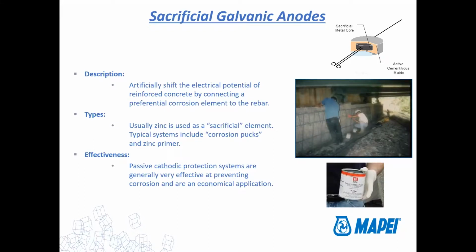It's going to be time limited depending on how much zinc you use. So typically 100 grams or so is kind of the average amount. But you can get anodes that are up to 300-400 grams of zinc. You can get them as small as some manufacturers are selling, like 38 grams. But the more zinc you use, the longer it's going to take for it all to consume itself. So the longer that anode is going to prevent corrosion around the patch.